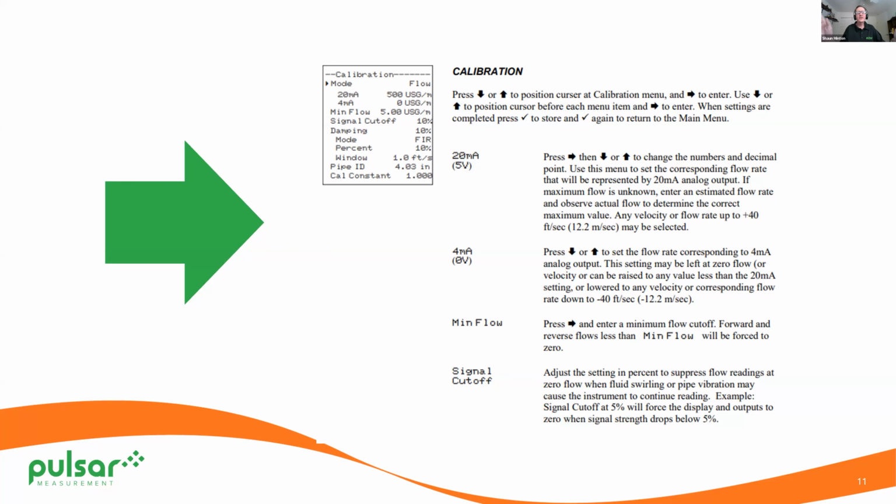If everything else is forgotten, if you can just go into calibration and get the proper inside pipe diameter, you can run this device. That's what makes it so cool. All this other stuff is just window dressing, but that's the most important thing. So make sure you have an accurate inside pipe diameter.